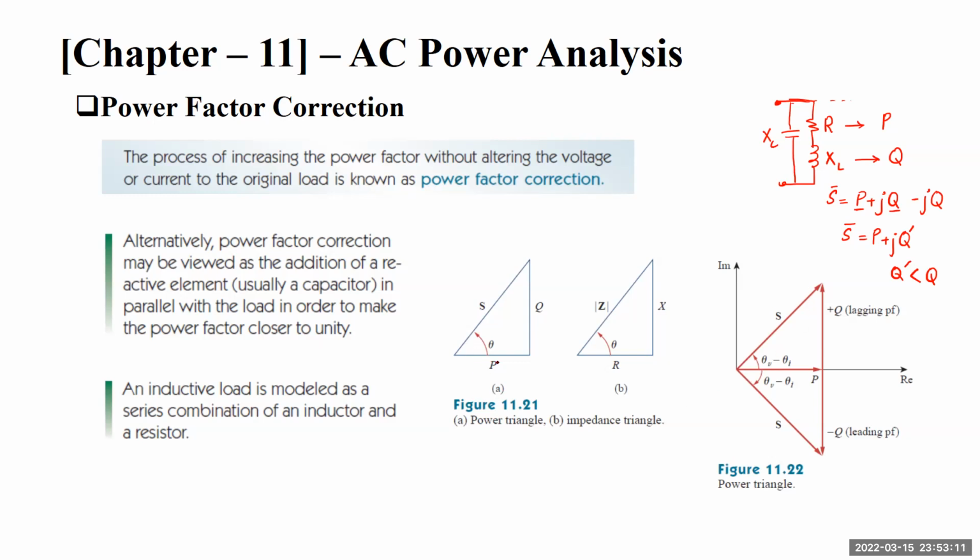Similarly, we have a power triangle. We have seen this in our last lectures. We have power across the x-axis. The Q, or reactive power component, is orthogonal to the useful power in watts, which is over there. Remember, the units for power are watts, the units for Q are VAR, volt ampere reactive, and the units for S are VA.